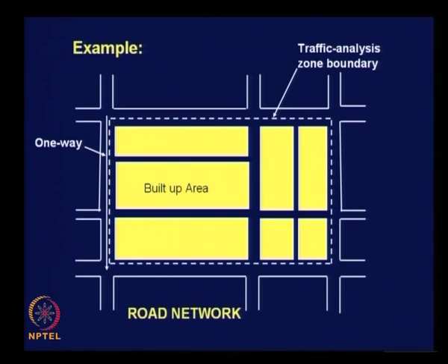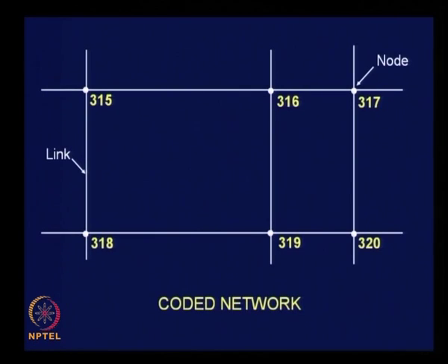And one suggested network for this zone is this. We have given node numbers for the road intersections, right. How many roads did we count earlier? More than the number that is shown here. You may recall we observed 3 roads in the east west direction, major roads, and one more minor road, totally 4, and we have considered only 2 roads in the east west direction, and there were a number of roads in the north south direction. We have considered only 3 roads.